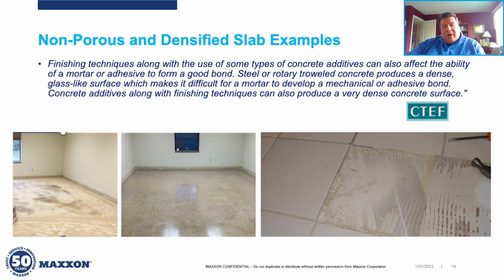And you see these pictures here that are included on this slide. So the first 2 pictures from right to left show a slab that's in the process of being polished, right? So this is a wet grind scenario in this first slide, that's leading to the finished result, which is shown in this middle slide. So you can imagine if at some point in time floor covering is going to be asked to be applied over a surface like you see in that center picture, there really is no porosity in that slab to promote a good bond.